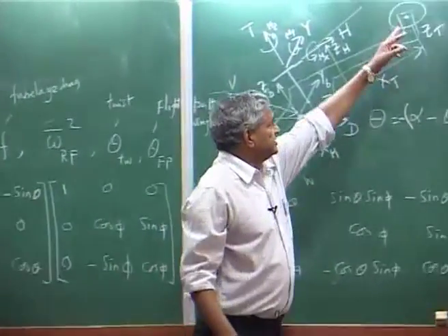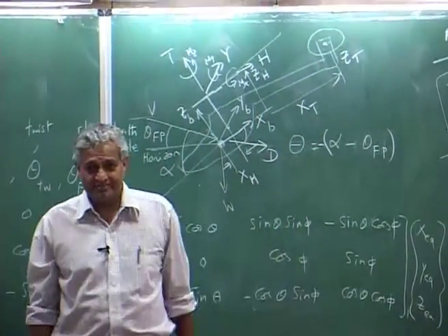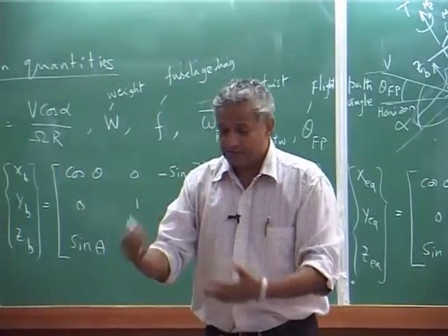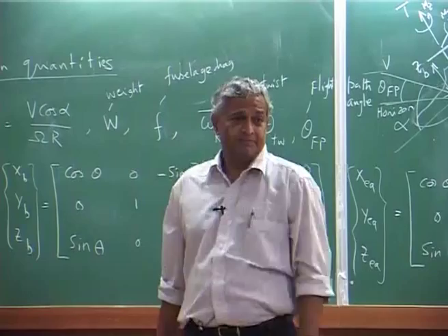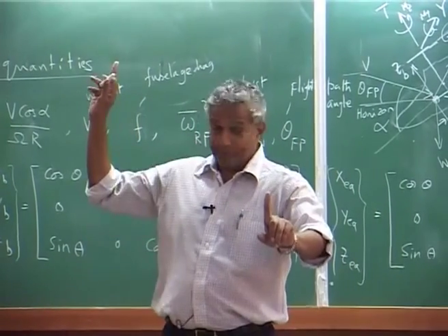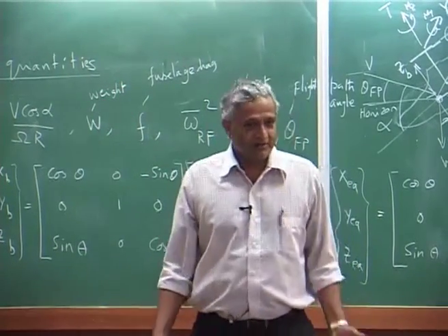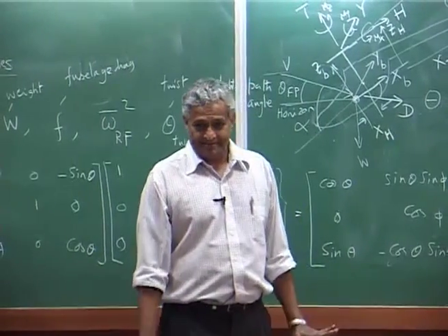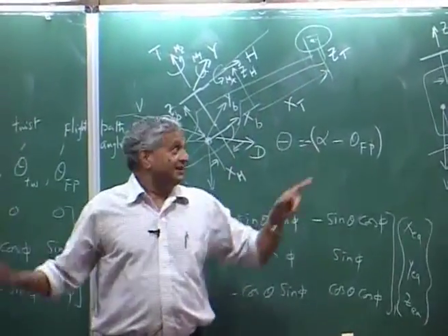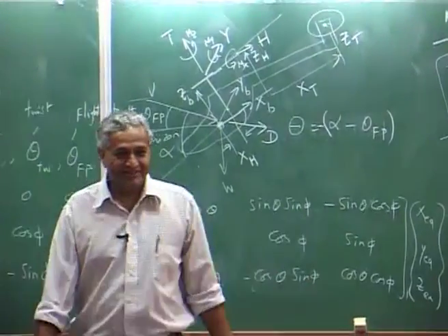You can say, well, I will put it here, and whatever you get, you have to take it, because you do not know how they will interact, the wake from the main rotor and the tail rotor rotation. So, best is you put it up. Even in a tandem helicopter, you see the back one will be up, the front one will be a little lower. This is to avoid that, because you do not know honestly. But some helicopters you may say, oh, our model has not lifted, it is right on that. But we take it, that is all.